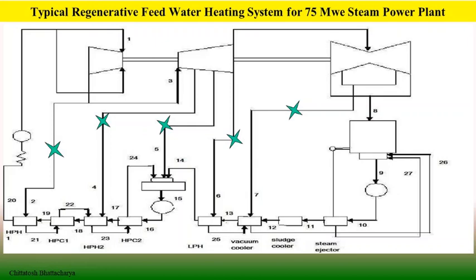demand. The major amount of HP turbine exhaust is going to the IP turbine, and HP heater 1 is heated with the extracted steam before entering the IP turbine. The extracted steam is also used for heating the boiler feed water tank attached to the deaerator, which is a direct contact open heater arrangement. The IP turbine exhaust steam is used for heating the condensate in the LP heater. The major part of the IP turbine exhaust is further expanded into the low pressure turbine, and this is discharged into the condenser hot well.